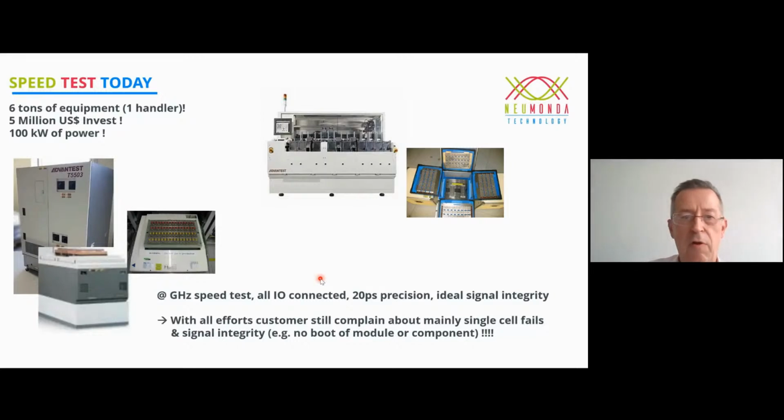So a lot of test effort: burn-in, array test at low temperature and high temperature, speed test at low temperature and high temperature. With all this high complexity and investment, customers still complain the quality is not good enough, especially in the module business, with ECC, with error correction. The servers notice if there are single bit fail events. So you get a lot of feedback that there are still sometimes single cell fails.